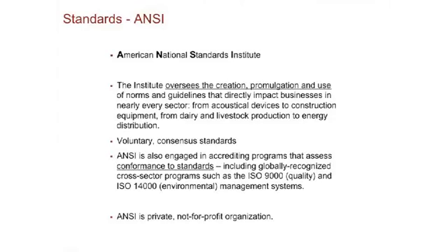There's another example, and again, you can just read it. I don't want to go through the details because this is just a sample of what you might find. But in the note, it says this is a grounding system to be used on energized electrical equipment, ASTM F855, 1990 edition. Now, your temporary grounding on de-energized electrical lines, based on the CFR, has to comply with this. And I've been involved in cases regarding this. Because now it's in the CFR, this is a law.